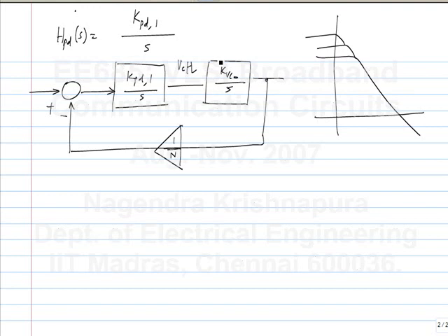You can make that K_PD by s plus something. Let's see if that works. So instead of a pure integrator, we will make it K_PD by s plus omega_PD. Clearly, omega_PD has to be small because we'll have a high Q. Let's study that. Okay. Are you all familiar with stability analysis?